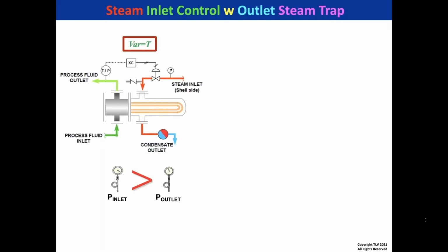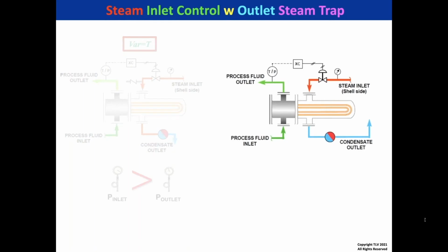You just have steam inside the exchanger or the reboiler. You're just going to vary the temperature of the steam by adjusting the pressure. Everything is great. Yeah, but that's not the real world for refineries and chemical plants. Come on, we're elevating the condensate 20, 30, 40 feet overhead into a return header that's got 25 pounds, 30 pounds of back pressure.